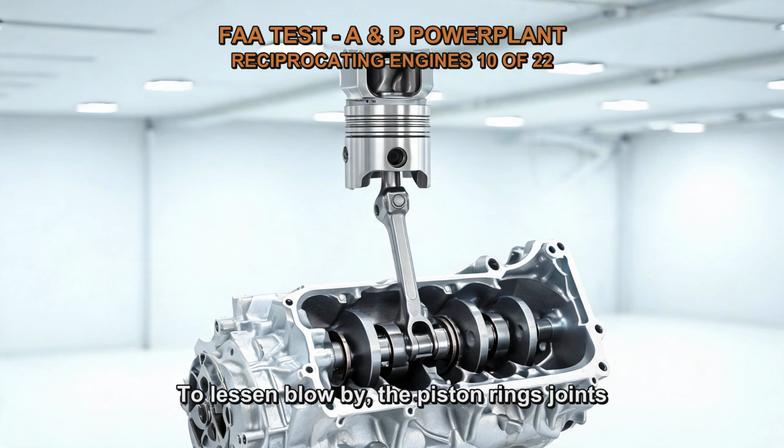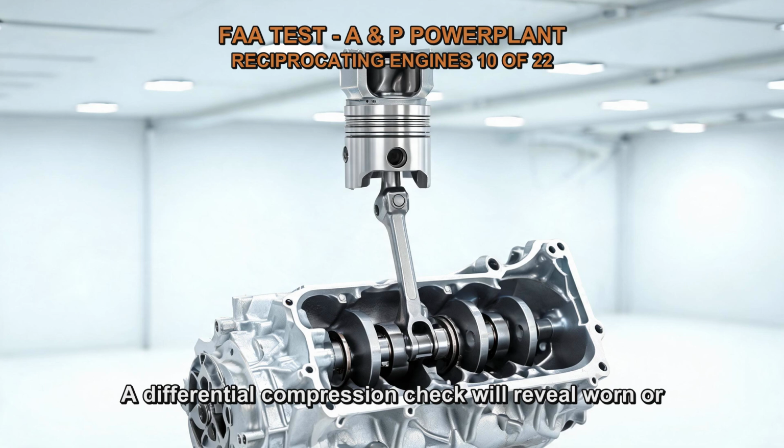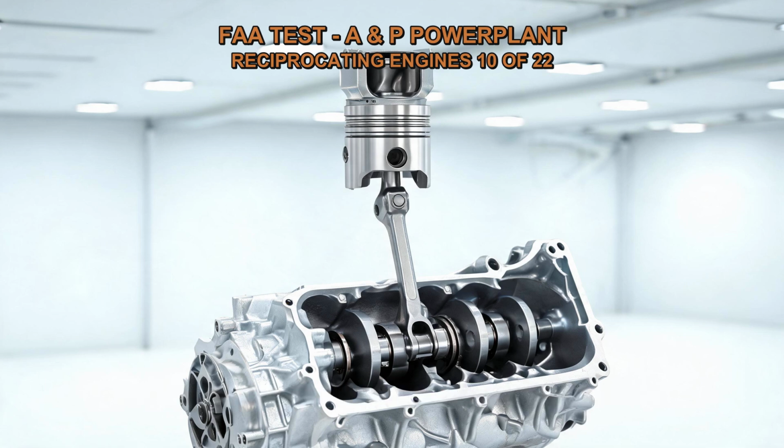To lessen blow-by, the piston ring joints must be spaced out around the diameter of the piston in which they are fitted. A differential compression check will reveal worn or damaged rings if the gaps are not staggered.